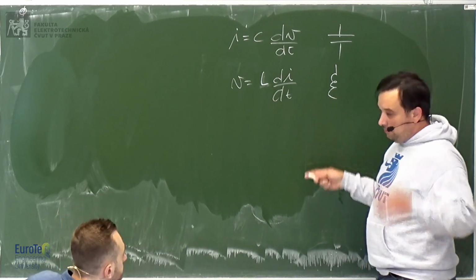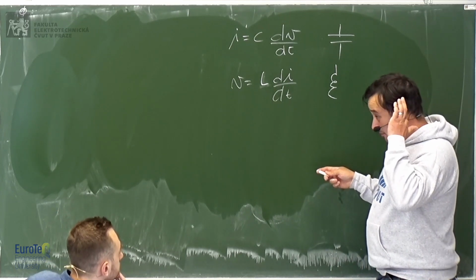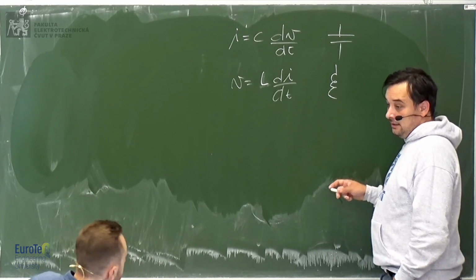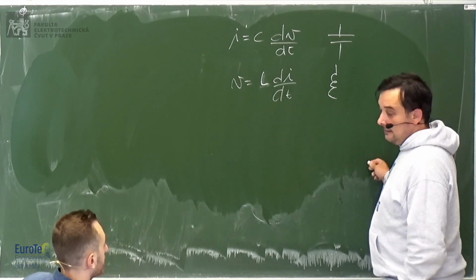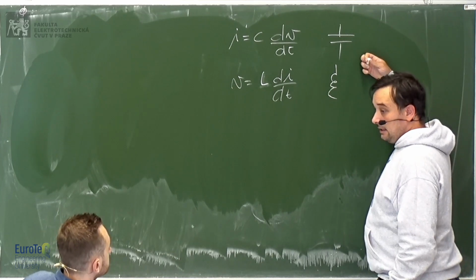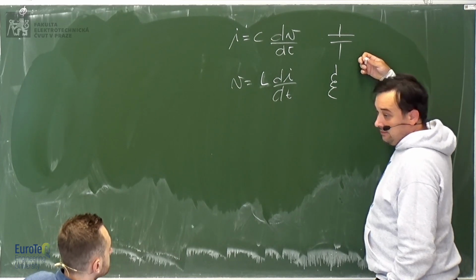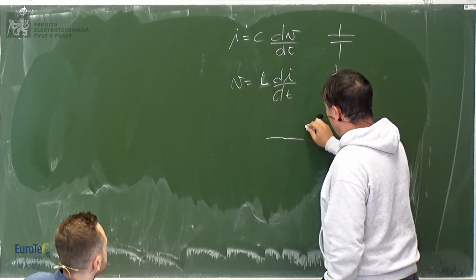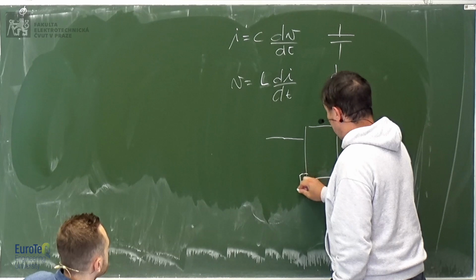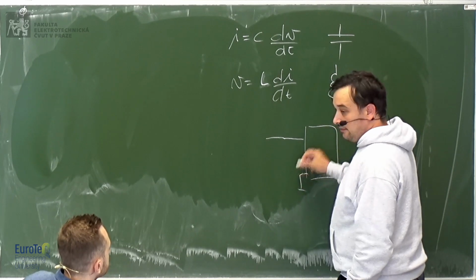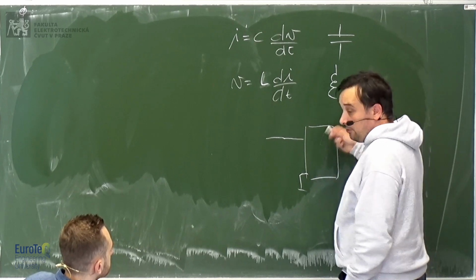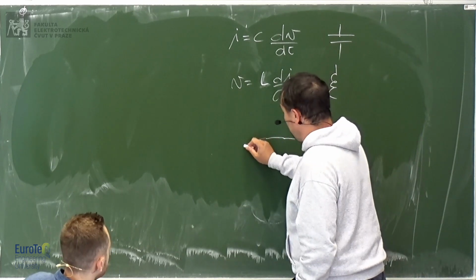So how do you use the inductors? Often in circuits, if you want to smooth out some current, you just put an inductor. Current ripple. For the capacitor, you put them to smooth out the voltage. So if you have a circuit and you want to connect something powering up some electronics, you have a sort of voltage source.